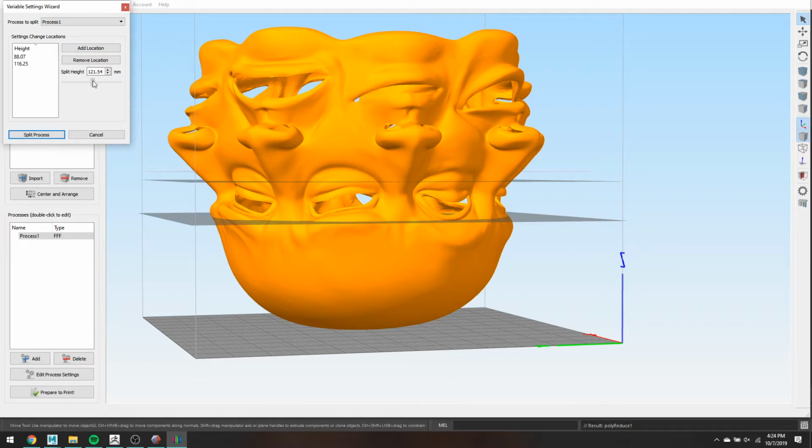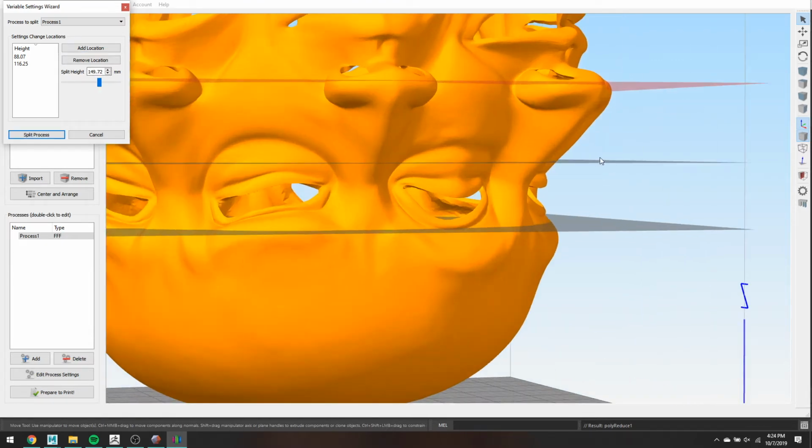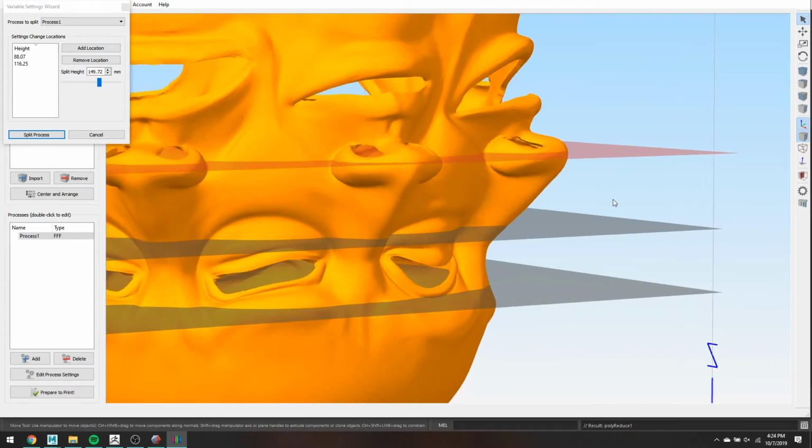And then the other place on this, which, strictly speaking, my print failed and I had to re-slice the bottom half of it, but this should print supportless on the nostrils. It's a super aggressive overhang, so right below that I'm going to do another location, and right in here I'm just going to print at a 0.1 millimeter layer height because I don't want that to fail, but I also don't want to use supports because they take forever.